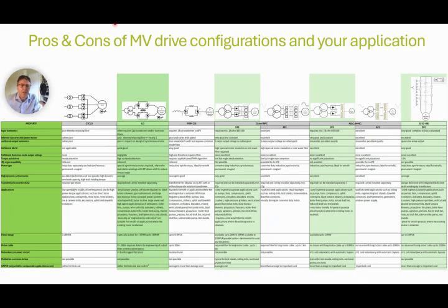The inherent power factor in the case of CCV and LCI must be corrected through a filter. For the PWM CSI, the active front end will be required to correct the poor load and speed dependent power factor. The drives from the 3-level up to multi-level relying on the direct front end have an excellent power factor over the whole speed range.